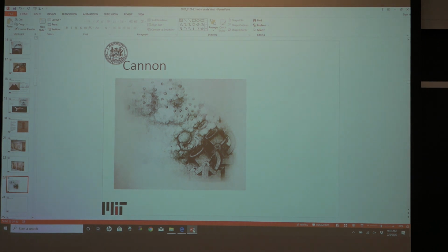Anyway, I'll show it to you at a different time, but what you're going to see on the surge stall is that when the blades actually came out of the back of the engine, it's essentially an explosion out the back of the engine, and they have cameras set up to show the rear view of that surge stall condition.